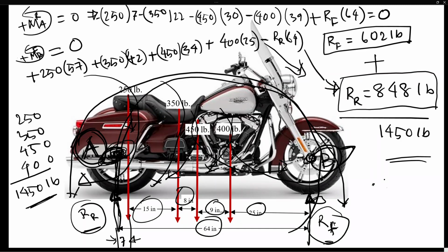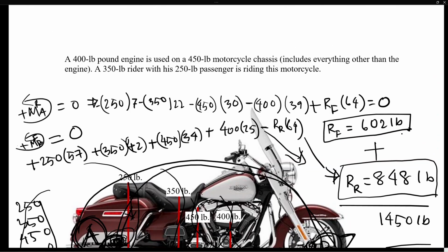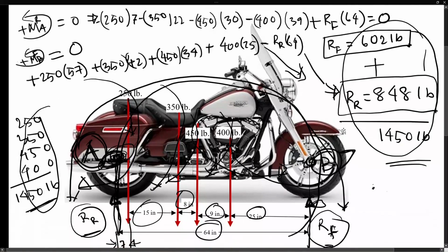So you take moment twice to calculate the reaction forces at two different places if it's connected at two different points. And then you also need to verify that adding all the external load should be the exact same as what you have calculated using your moment formula.